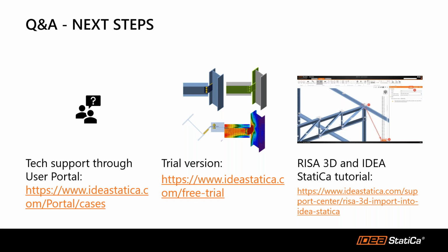The reason we're adjusting the global coordinate system for the vertical axis is because that's how the SAF file is created. So unless it's changed, if you don't change the vertical axis, you will get an error message from RISA stating you have to change it before you can export the SAF file. Okay, gotcha. How about another question?